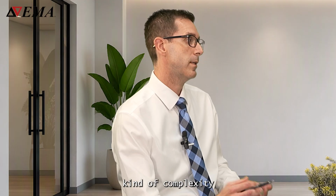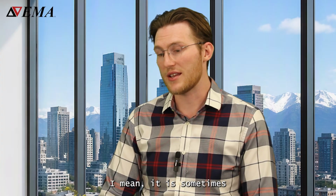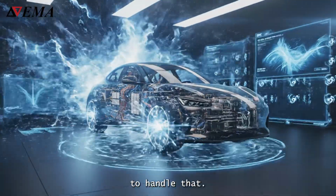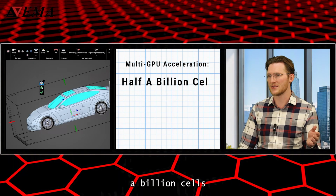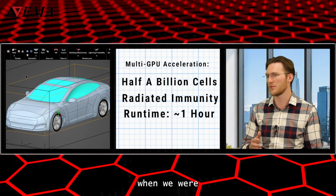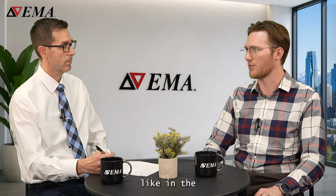If you put that kind of complexity in, I would imagine you're approaching 1 billion cells. How could that be computationally efficient? Yeah, it is sometimes approaching 1 billion cells, but with that GPU acceleration that I talked about earlier, it's computationally efficient to be able to handle that. Anecdotally, some of the full platform automotive models I've been doing recently were around 500 million cells, but we're still running radiated immunity in a matter of an hour with multi-GPU acceleration. When we're getting on the order of 1 billion cells, multi-GPU helps us keep that well under a day still.